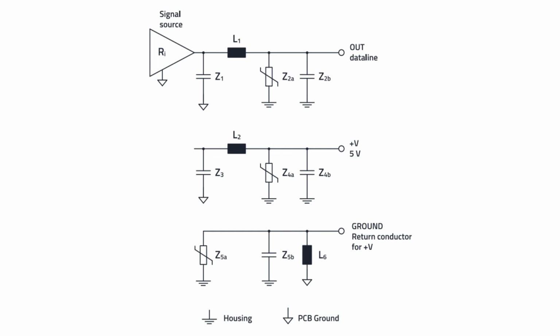So first, we're going to discuss the EMI filter of an asymmetrical signal interface with transient protection. While unbalanced signal interfaces only use one data line per signal, interference emissions and interference immunity requirements are generally higher than with balanced signal interfaces. In our first image, we are seeing a possible filter circuit for attenuating interference emissions and ensuring interference immunity.